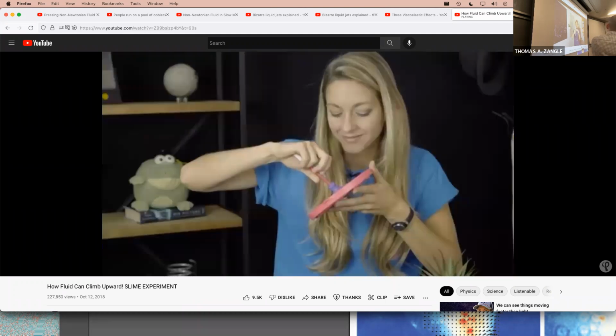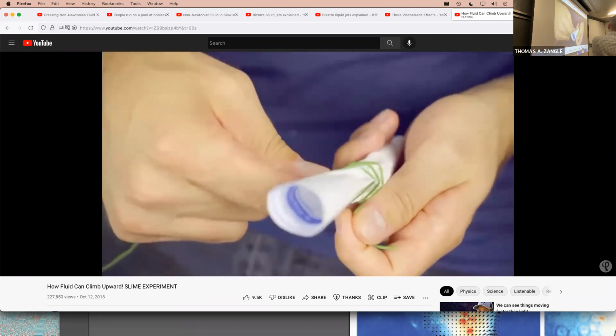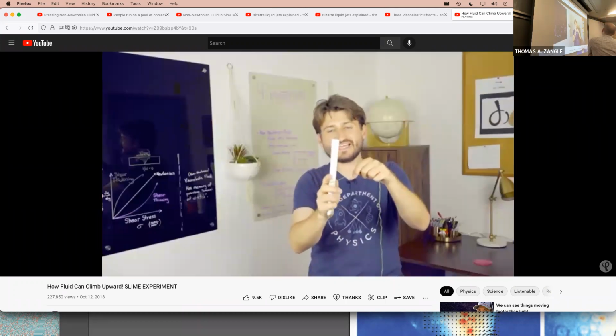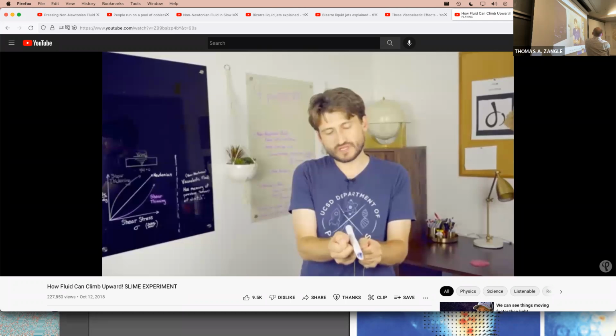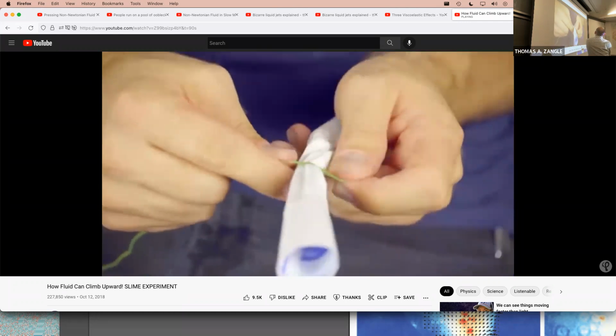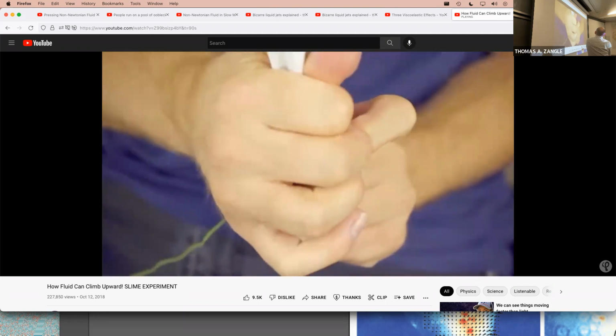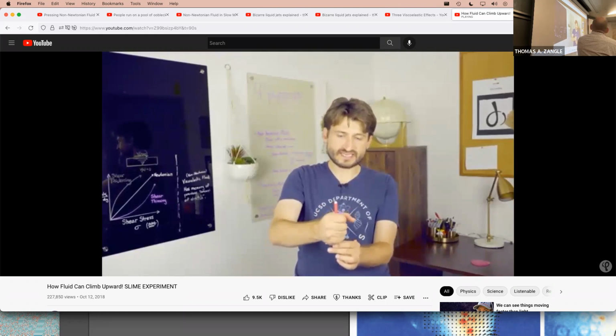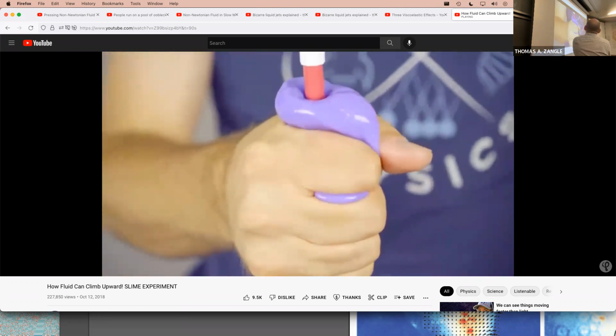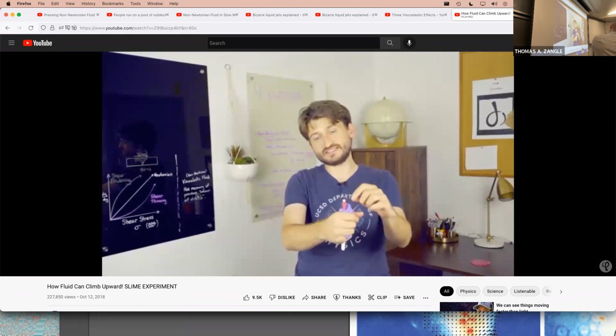So as it turns, it wraps up this string with fluid and it's tightening as it goes. That creates a tension. When you have a tension that's pulling around, it actually creates an inward force that causes it to collapse. So think about what's going to happen when this cylinder of fluid starts to squeeze. The effect is essentially the fluid squeezing itself up the rod.